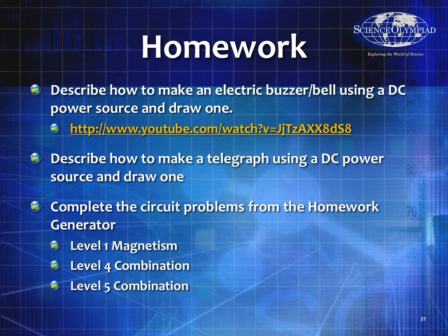However it strikes the bell is going to basically turn off the electromagnet, so then the magnet stops. It falls back, and that completes the circuit, turns on the electromagnet, and causes it to hit again. This is a very, very common practical and a very, very common question on tests.